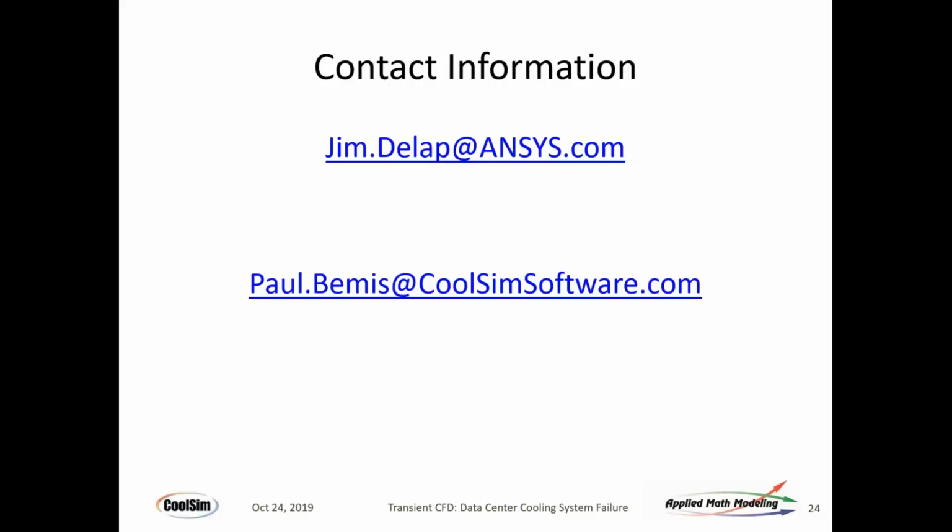So here's a question: how is the air on the inlet of the rack modeled? Is it uniform? Does it vary with time? In CFD, we model it just the way it is. It does vary with time. It is non-uniform. So the air inlet on the front of the racks is non-uniform. That's the value of CFD, is modeling the entire gradient of air in the room. It can be as a function of time. It usually resolves to a steady state condition, however. So we generally do it in steady state.